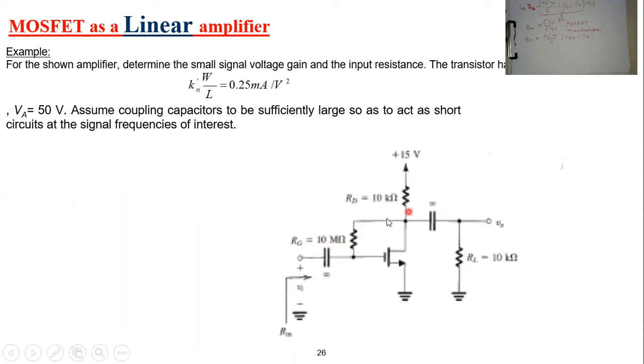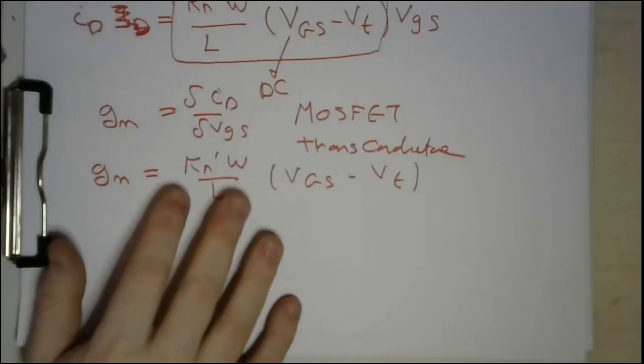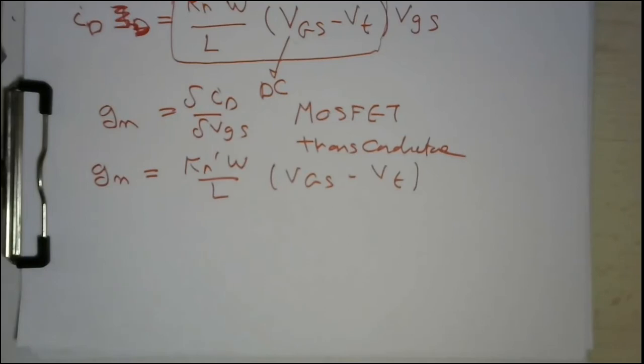So these two capacitors are a short circuit in AC, and an open circuit in DC. I will first copy and paste the circuit into our whiteboard, and then we will start together the journey of solving this circuit step by step. Again, this is a very important example in our module.